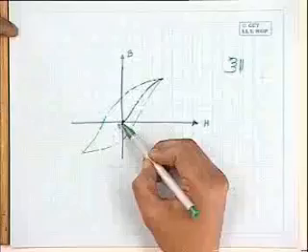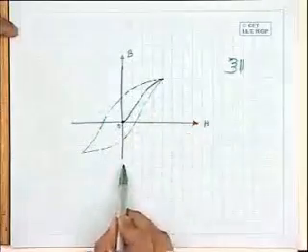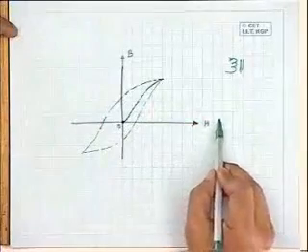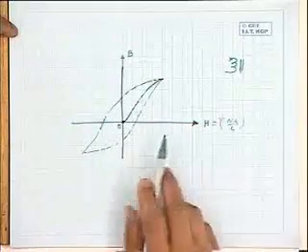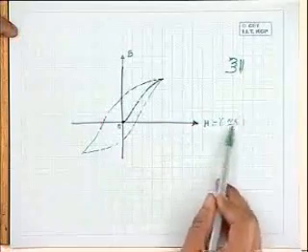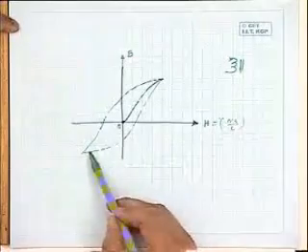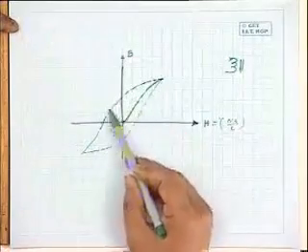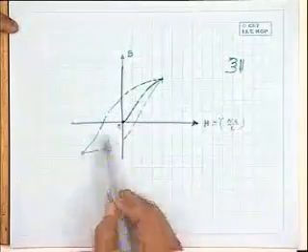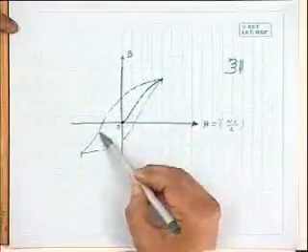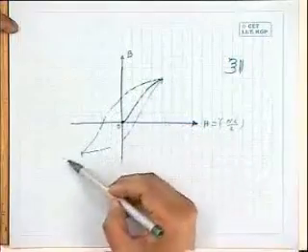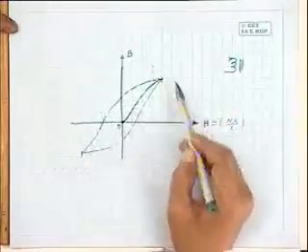Now, I want to find out whether there will be any power loss when such alterations go on in the current. So, current is alternating in nature. Now, H is what? Ni by L. N and L are constant. So, direction or frequency of the current will dictate how fast and to what extreme two values it will oscillate.